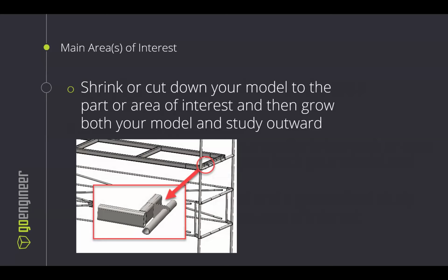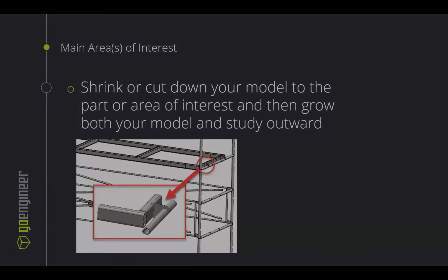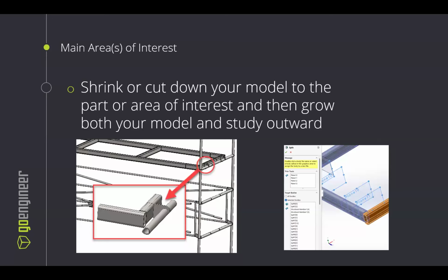This is the classic approach. Start simple with the main component of interest. In this case, maybe I've taken those 5 components of the scaffolding. I can split them up using SolidWorks features, like the split part function, which is pretty amazing. I use that quite a bit. If you're splitting components in simulation, even though they split, whenever you attach them, you have the ability to have a continuous mesh and have it kind of arm wave ignore that boundary. So we have some flexibility, even if you split the model quite a bit.